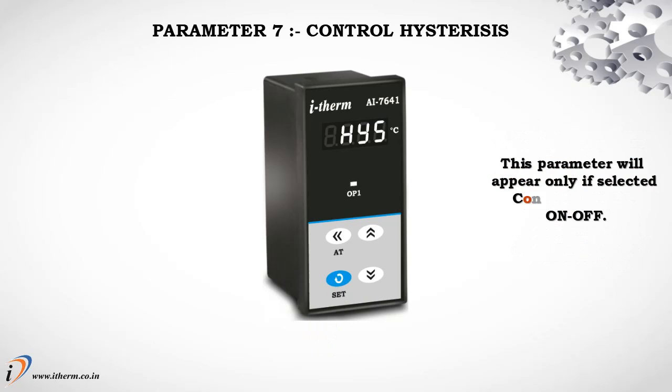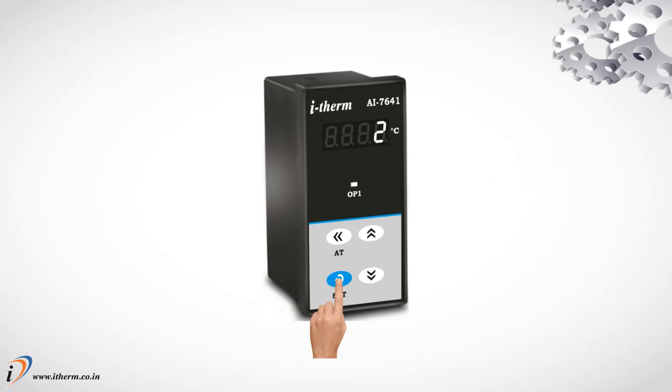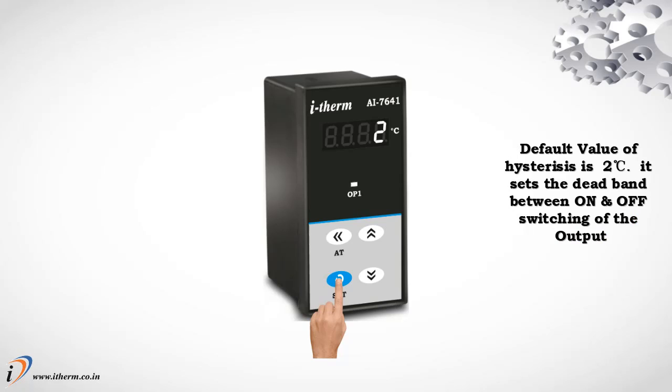Parameter 7, control hysteresis. This parameter will appear only if the selected control action is on-off. Default value of hysteresis is 2 degrees centigrade. It sets the dead band between on and off switching of the output.